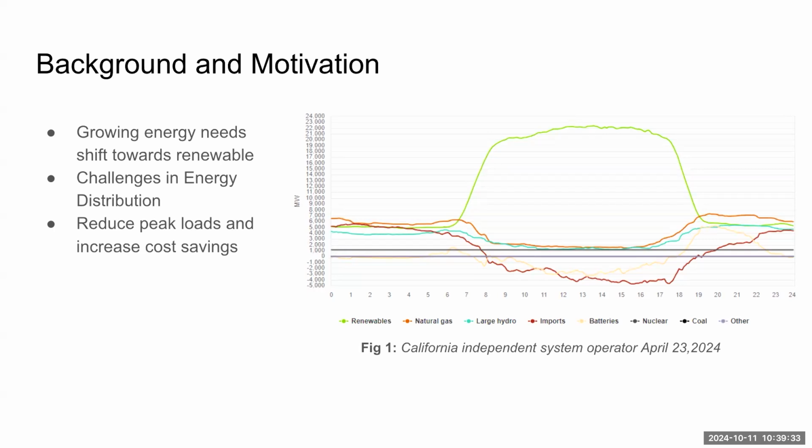Okay, so motivation for us is we can use more batteries to balance all this out, and that works for sure. But batteries are expensive, and so another way to balance this out is with controllable loads. So you can try to shift loads around so that maybe you shouldn't charge your electric car here because that's the worst time of the day. You should charge it over here. Or you run appliances, you pre-cool the building during the day. So there are many options of shifting loads. And so that is one of the challenges of our new power system, as we want to shift more loads, but we haven't done that very much at all. We've just shifted a few AC loads in the past, but not the vast amounts of loads that we have now.